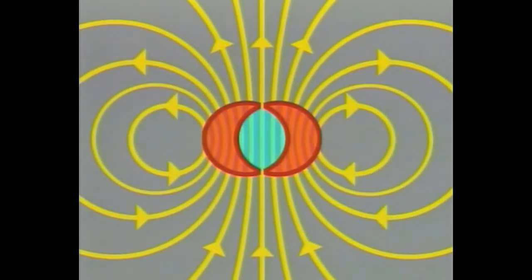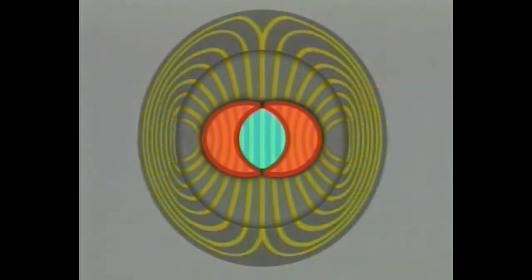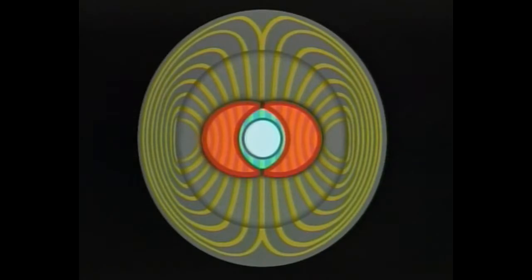To contain the action of these forces, the conductors which carry the currents are fastened in collars made of non-magnetic material. By surrounding all the conducting collars in a yoke made from a magnetic material, iron for example, the lines of the field are confined, and thus parasitic magnetic fields are avoided, without affecting the field in the useful zone inside the tube, shown in white, in which there's a perfect vacuum.